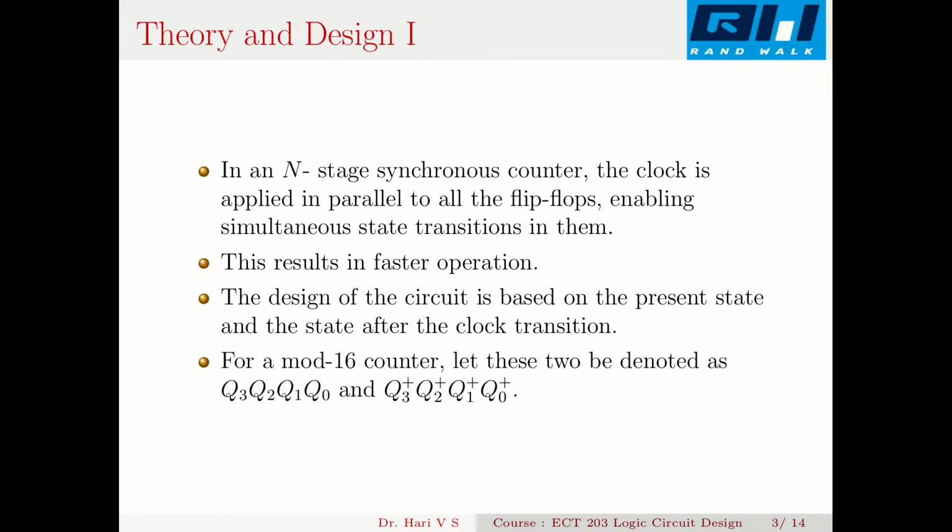Now when you come to the theory and design, in an n-stage synchronous counter, the clock is applied in parallel to all the flip-flops, so that enables simultaneous state transitions. That results in faster counting or faster operation. The design of the circuit is based on the present state and the next state. The next state means the state after the clock transition.